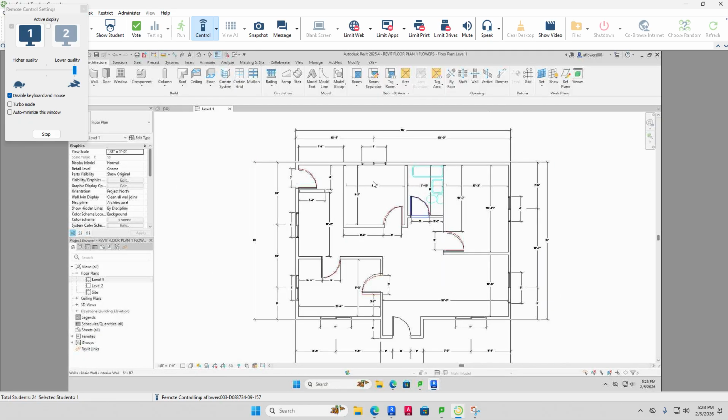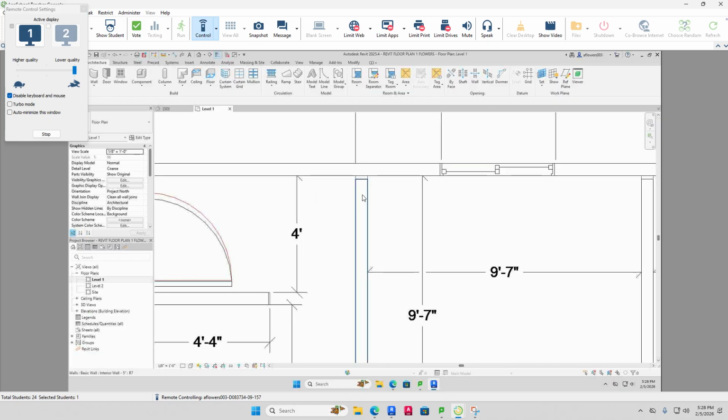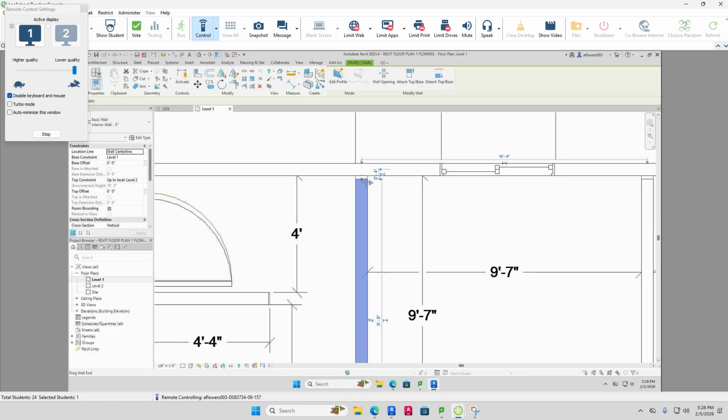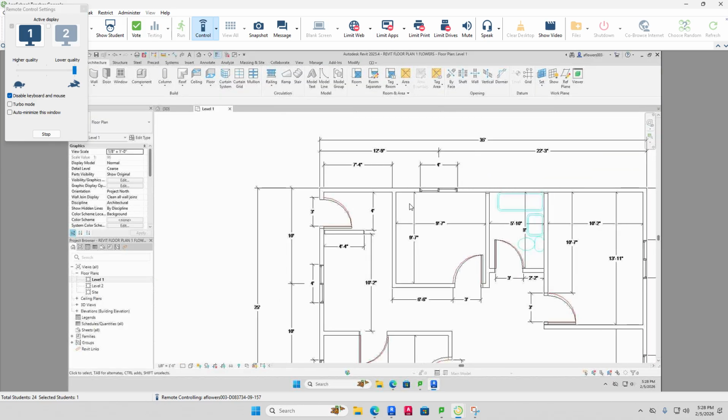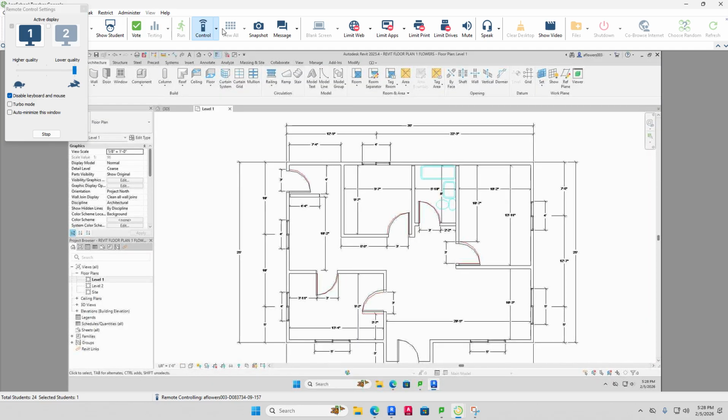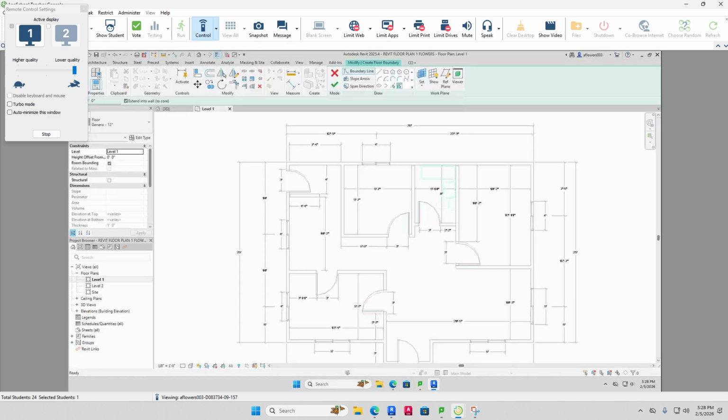So I'm going to do one thing here because this actually should be pulled up to here. All right, we'll do that. Okay, and we'll try that again. I'm going to hop out here and just view it. Okay, so go ahead now. Go to your floor there, Alan. Let's try that again. You want to change your floor type to your wood joist, wood finish, and then just hover your cursor on the outside wall and click, yep, and you should be good to go.